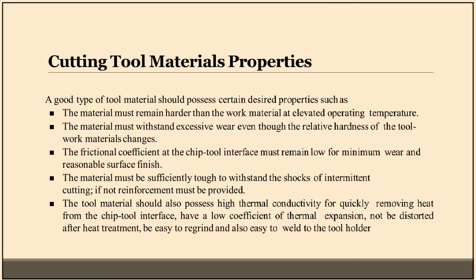Number 5, the tool material should also possess high thermal conductivity for quickly removing heat from the chip tool interface, have a low coefficient of thermal expansion, not be distorted after heat treatment, be easy to regrind and also easy to weld to the tool holder.